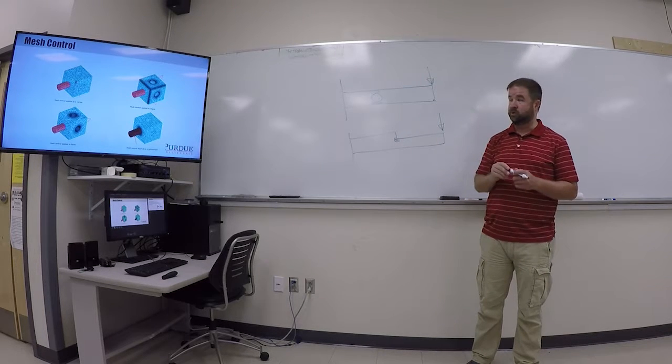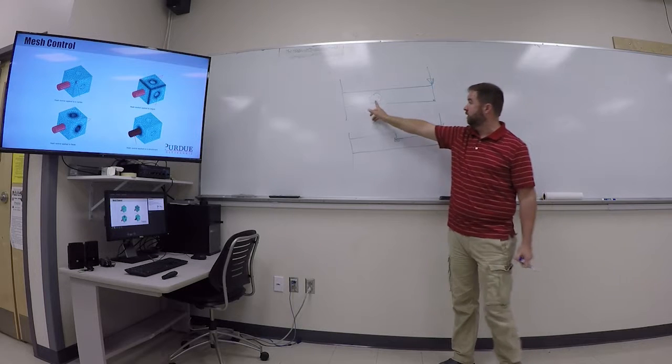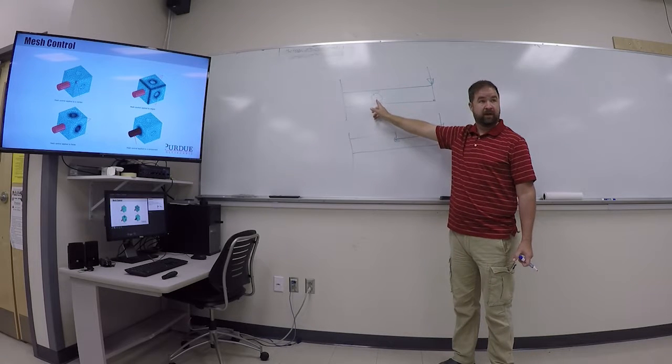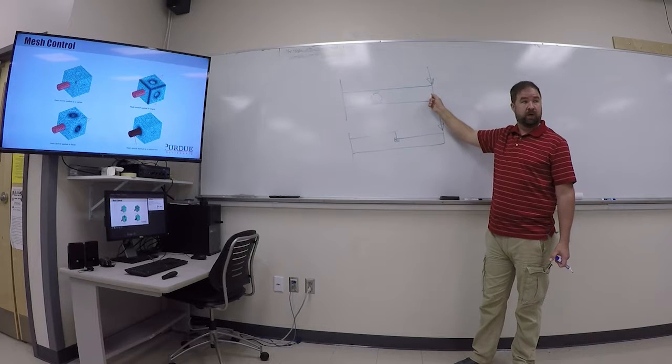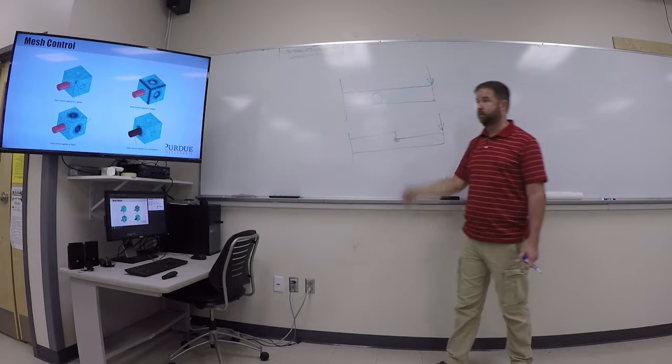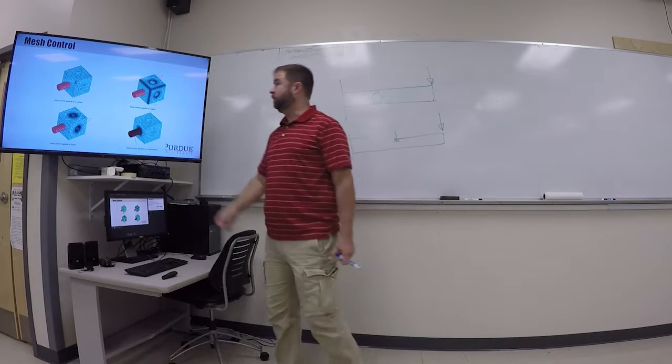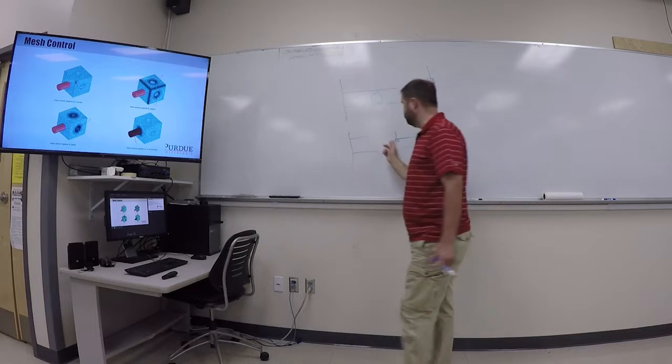So this mesh control concept allows us to reduce the element size in the areas where I know the stresses are going to be high, but leave them big over in the areas where it's really low anyway, and I don't care what it is. Okay, so that's the point of doing this. You want to refine the mesh in the areas where there's high stress.